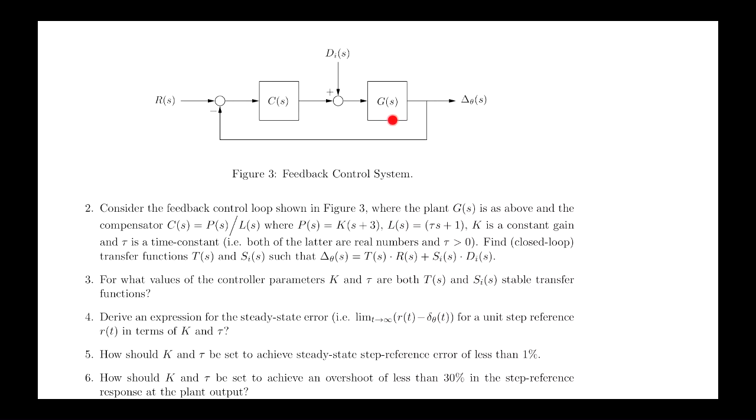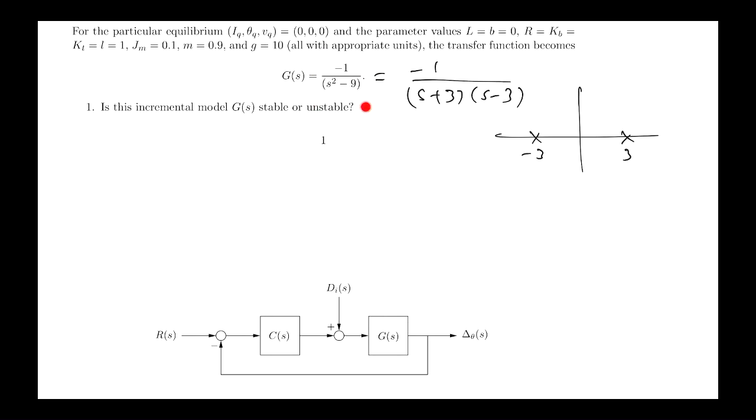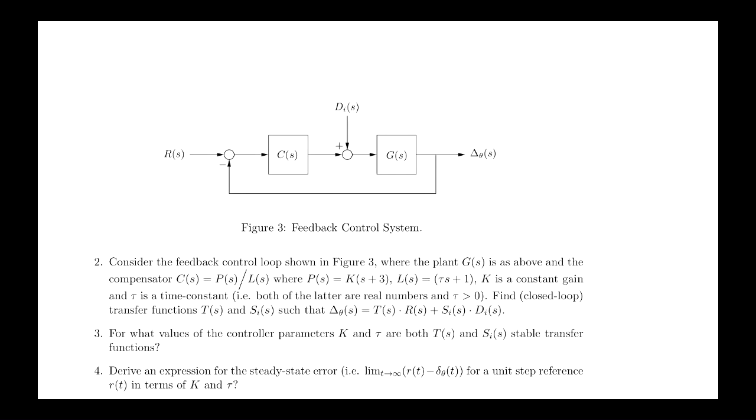The first part actually doesn't require you to put anything in for G(s), but later on we'll be putting this in for G(s). So we've got a control system here that measures how far you've moved away from the equilibrium value of 0, compares it to a reference value, and generates an error signal which goes into a controller that produces a signal. That gets combined with a disturbance input, whatever's pushing on the top, which then drives the dynamics of the inverted pendulum. What we want this closed loop to ensure is that the output follows the reference, even when there's a disturbance acting on the system.